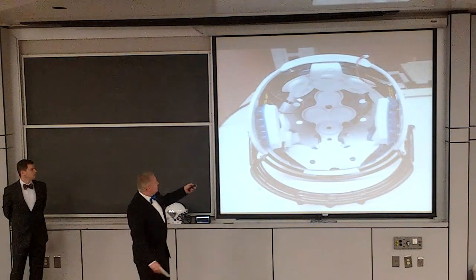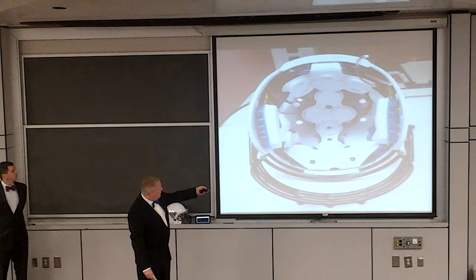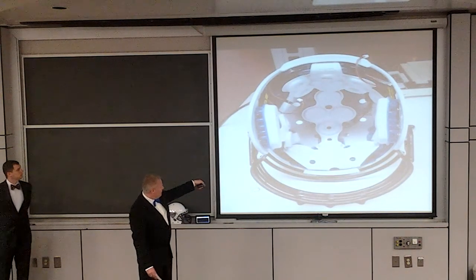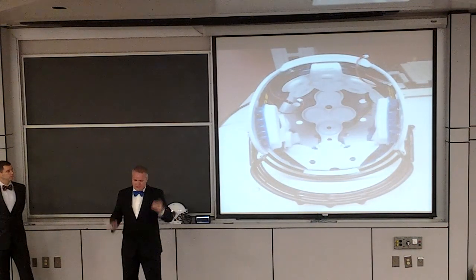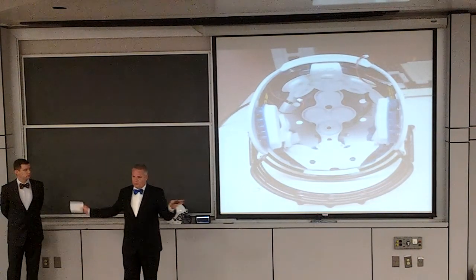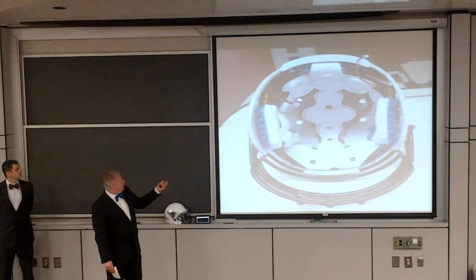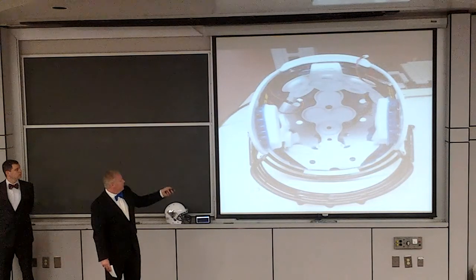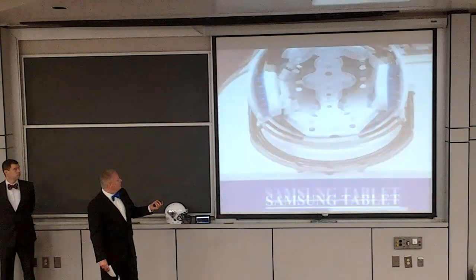Now this is a better picture now that you've seen the actual components. So back here, behind this padding, you have the Bluetooth and the Arduino. Up here at the front is where the accelerometer would sit around the top of the head. So if the player was standing vertically upright, the Z would be up, and X and Y would be straight in front of you and to your right. And back here are your batteries, which are out of the way, and behind. And all the wiring is done behind the pad, so they do not interfere whatsoever with the player's ability.